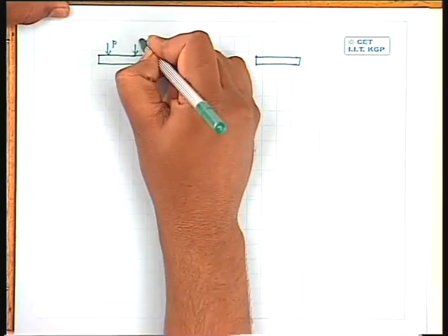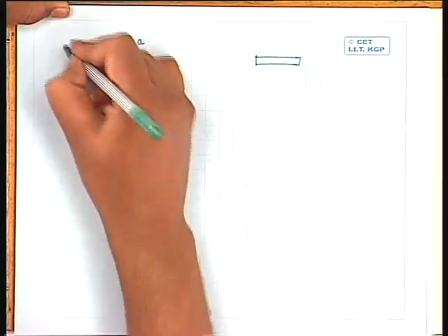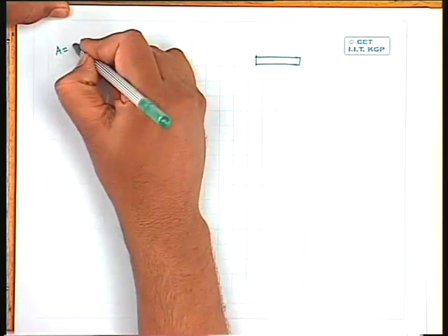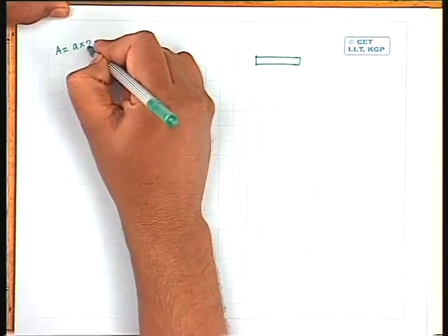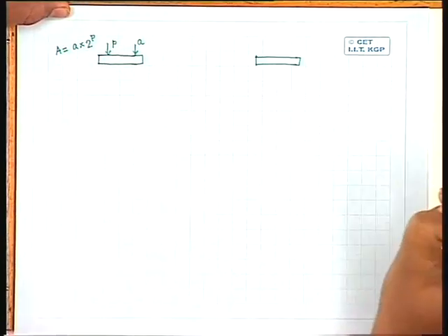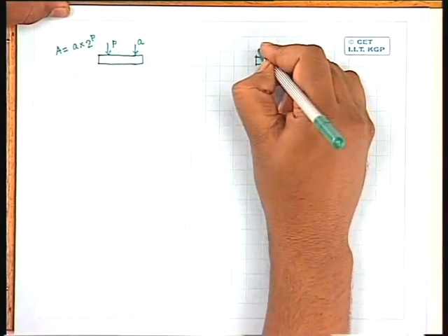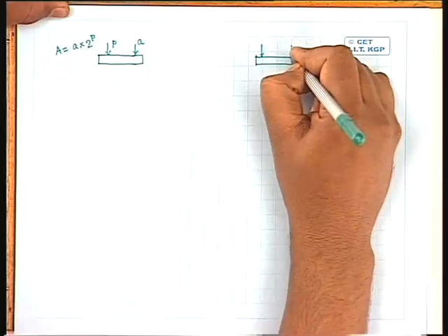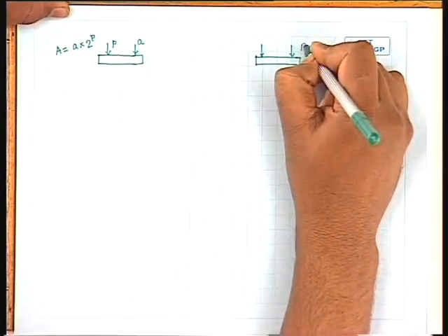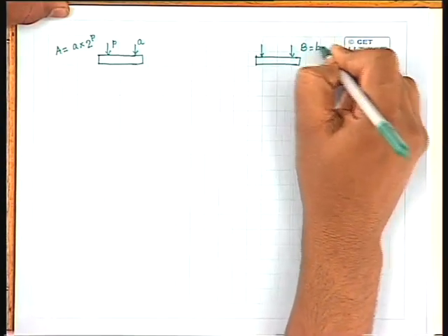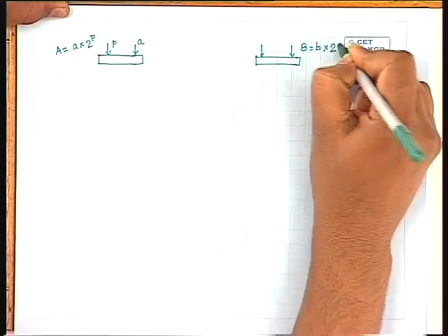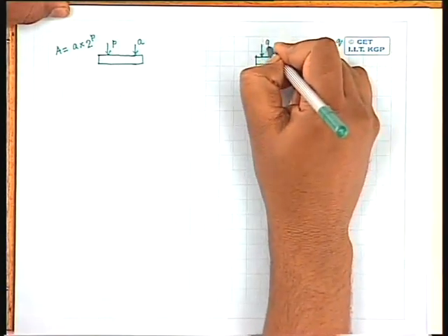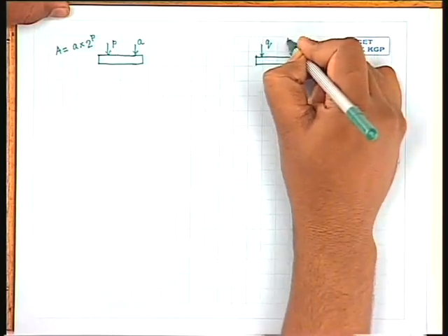So exponent part P and fraction part A, because we have said that we have to add number A equal to A into 2 to the power P. This is the first number. And the second number that we want to add is number B, which is B into 2 to the power Q. So this will also take exponent Q and fraction B as input.